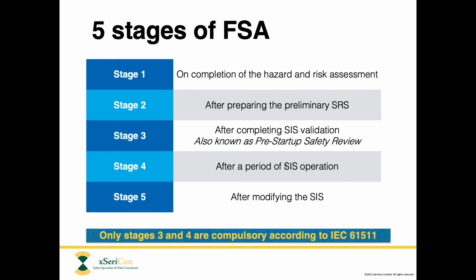And then the fourth type of confirmation activity is a functional safety audit. Now, this is very similar to any other kind of audit. It's focused on procedures. So the idea is to look at a procedure such as the functional safety management plan, such as the management of change procedure, the HAZOP procedure, the configuration management procedure, and whatever else there is for the functional safety system. And each procedure needs to be audited to confirm that there is evidence that the procedure is being followed properly.